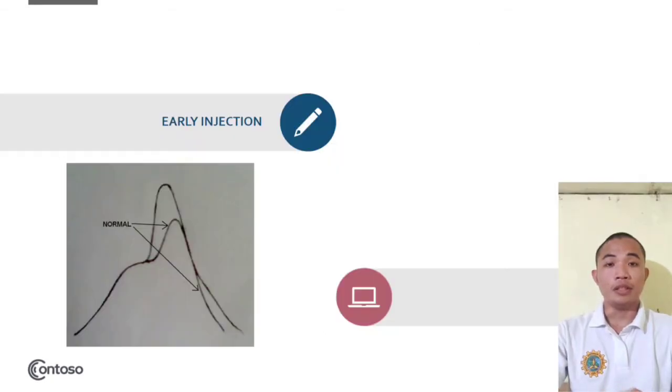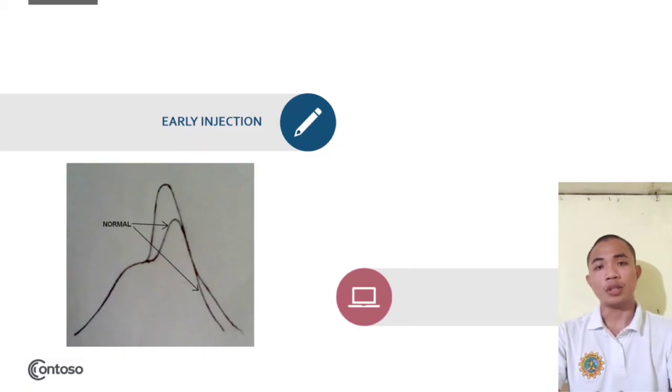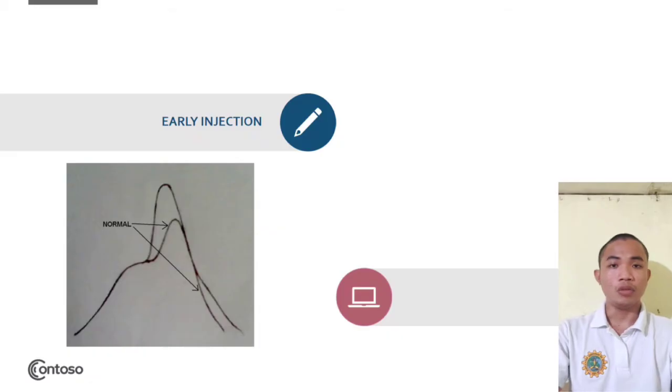First, let's tackle the early ignition. Based on the diagram, the abnormally high peak pressure of the unit is recorded at the top of the piston stroke, and it's because of early ignition causing combustion to start long before it is supposed to. Also, there is extra pressure at the end because of early ignition. And it can cause a knocking sound which comes out of the engine due to heavy loads which is passed to bearings via running gear.